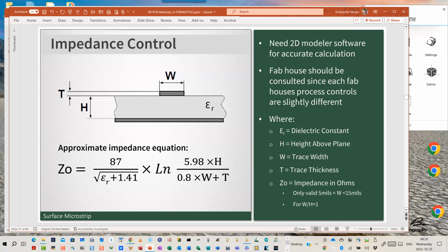Okay, so when I'm doing controlled impedance stack ups professionally, the first step I do is build my stack up, and before I ever lay my first trace on the board, I send the stack up to the fabricator I'm going to use and say, verify my stack up meets all of your process, and tell me what adjustments you'd like to see. And if they come back with any adjustments, I feed those into the tool, and therefore I know when I'm designing, there won't be any surprise gotchas when it goes through the fabrication process.